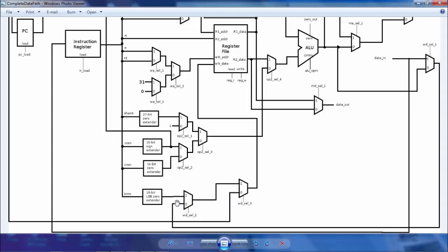If you just follow through this multiplexer chain, right? There is a WD selection 1 as well, which is either I can have data back from the memory or from the ALU operation. For example, an add operation writes back to the register the result of the ALU operation, right? So one data source can be the ALU operation. So that's the WD selection 1 that controls it.